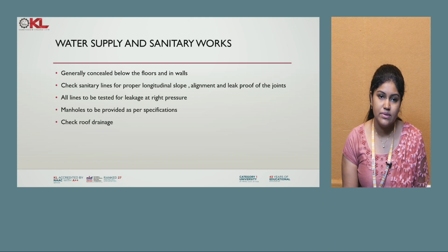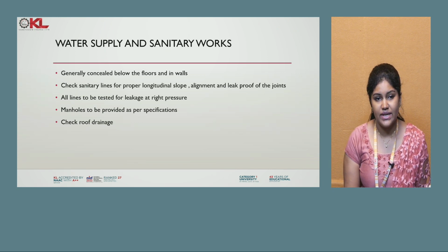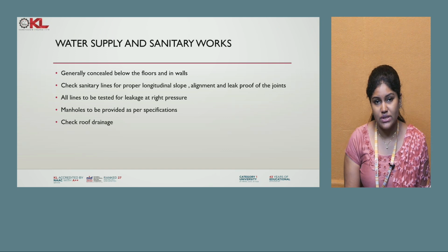Coming to the water supply and sanitary works. Generally concealed below the floors and in walls. So check sanitary lines. When it comes to the water supply and sanitary works, the proper sanitary line should be checked. That is whether the proper longitudinal slope is there or not, so that water can flow through the slope.